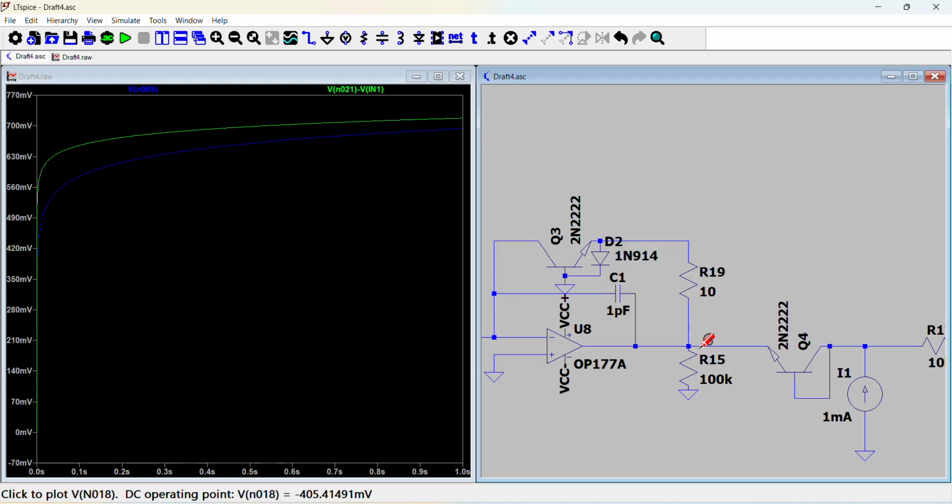And that causes an oscillation. Because at very high frequencies, if your gain bandwidth product multiplied by the feedback doesn't drop below 1, it feeds back the signal, but also it feeds back the signal at a 180-degree inversion because of parasitic capacitances inside of the op-amp.